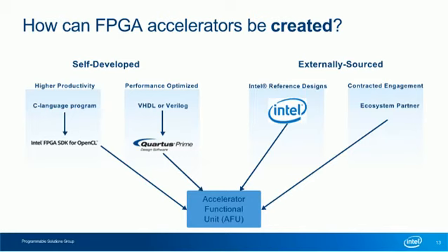If you're looking for a software-centric way to develop FPGA IP, the acceleration stack supports an OpenCL flow through the Intel FPGA SDK for OpenCL. In this scenario, Intel provides the OpenCL board support package, and all the user needs to do is develop and optimize their OpenCL kernels for the FPGA in the C-based environment. This approach makes FPGA development easy and accessible to parallel software developers.